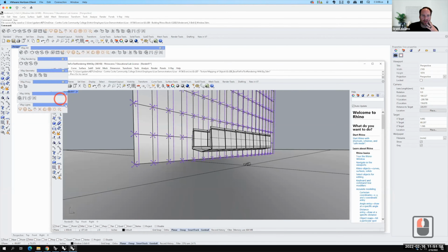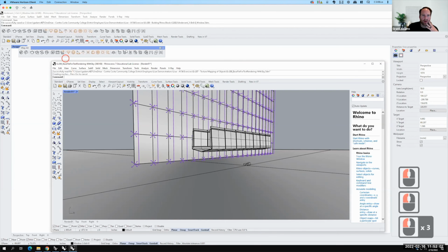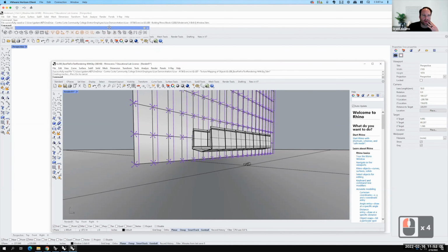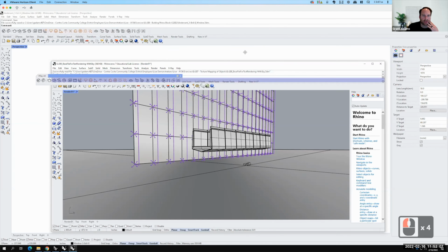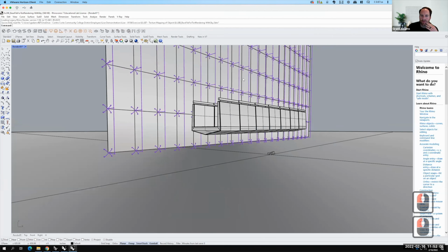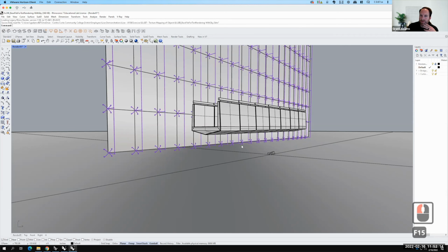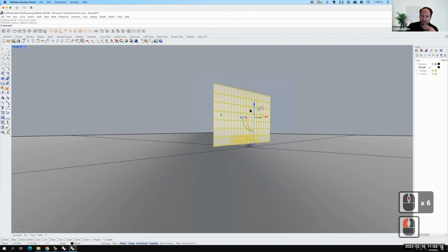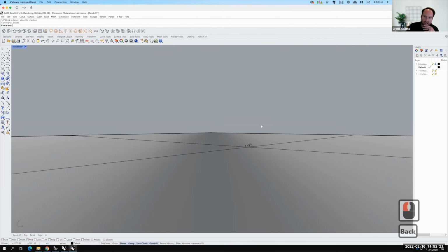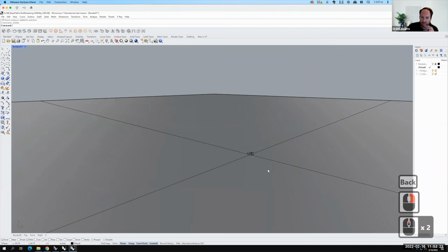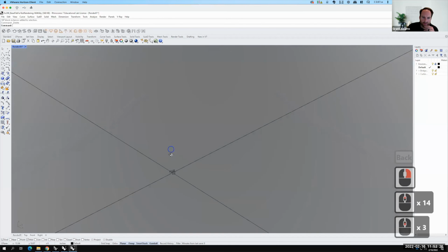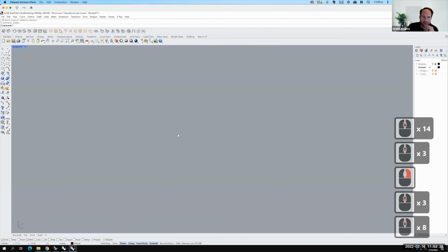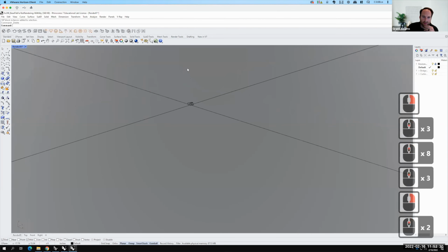All right, so this scene is already kind of set up for me, but I don't want to render out those windows. So let me get rid of all these pieces that I didn't need. The quickest way of doing it is to type SEL block instance, but I can also just select them all and then press the delete key and they're gone. Now let's bring in that window that I just created. Again, the reason that I'm doing this is because this scene already has the lighting set up for me.